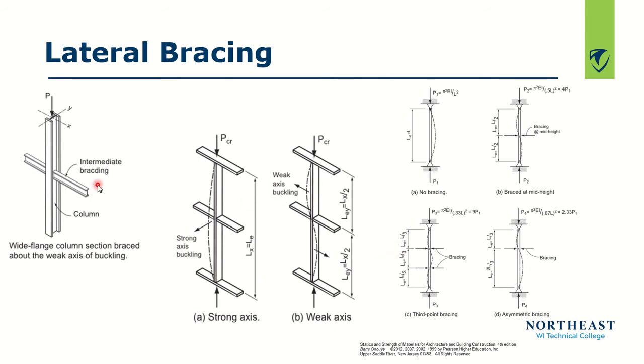All right, let's talk about bracing. As we know, when we load up a stud wall, which way is it going to buckle? It's actually going to buckle inside the wall. It's not going to buckle out, because the strong axis is this way. So L X, the length of my stud between top plate and bottom plate, is L E. Say I need to prevent buckling. That's why we put bracing in. What that will do is reduce our effective length. So it will help the weak axis.